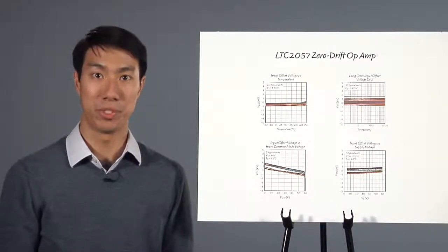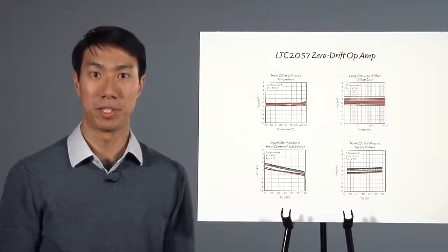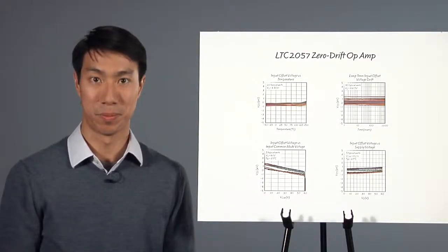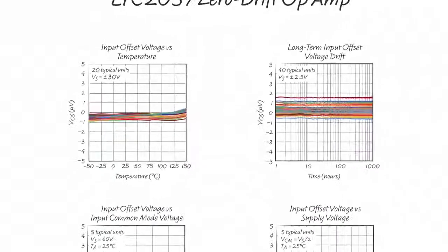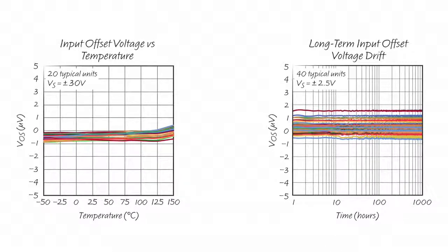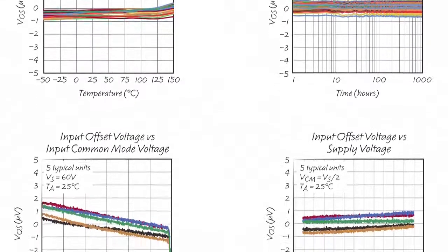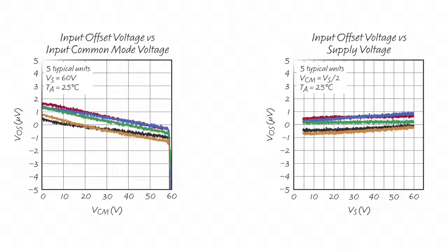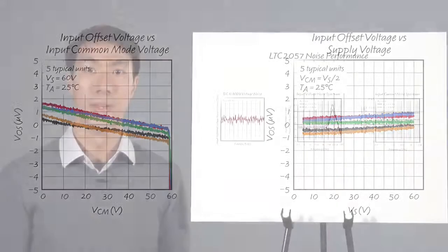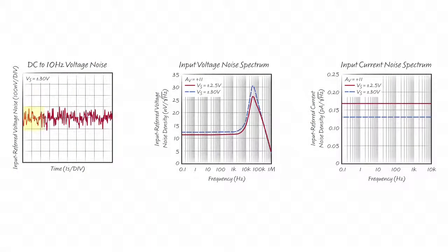In this video, I'll be demonstrating how to choose a zero-drift amplifier based on some lesser-known performance characteristics. As you may know, this type of amplifier is the ideal choice for high-precision sensor circuits due to its low offset and low drift under all operating conditions. High dynamic range measurements can be made over wide common mode voltages and high closed-loop gains with excellent accuracy and repeatability. In addition, zero-drift amplifiers have great low-frequency noise performance and suppressed 1/f noise down to very low frequencies. This complete set of characteristics will allow you to reduce or eliminate the need for periodic calibration.